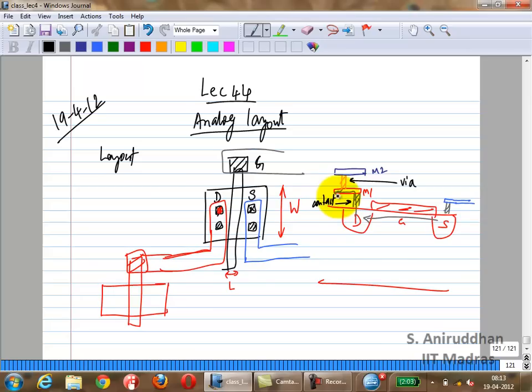We have shown the 3 layers. We have shown the drain and source conduction layers. The background is actually the substrate. So all of this area is actually just the substrate. However, the substrate resistivity could be high, right? Plus the connection of the substrate to the lowest potential could happen globally for the overall chip. So you need to give it local contacts.